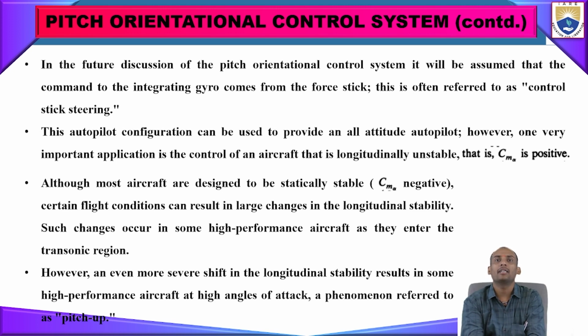So although aircraft are designed to be statically stable, that means CM alpha should always be negative. Certain flight conditions can result in large changes in longitudinal stability. Such changes occur in some high performance aircraft as they enter the transonic region. However, even more, longitudinal stability results in a high performance aircraft at high angle of attack.